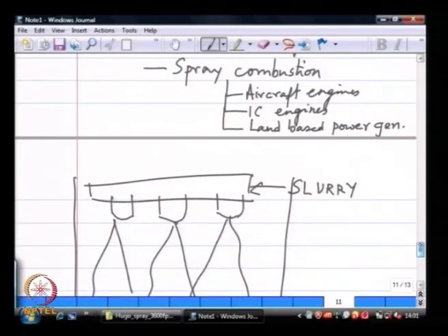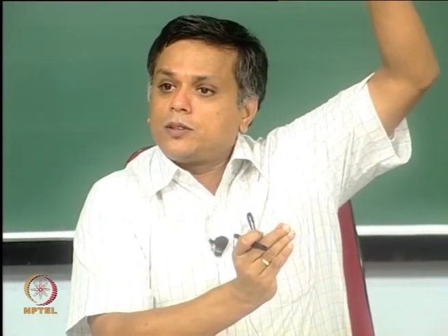Again, the objective of this is to increase the surface area. So, really speaking, I want to go as small as possible on the drop size, but the conflicting part of the requirement comes from the geometry of how you want to design this combustor. Say for example, I do not want a combustor that is too short and flabby. I want a slightly longer combustor, which means if I create a mist at my spray nozzle that is very fine, these drops may not penetrate sufficiently far into my combustor.